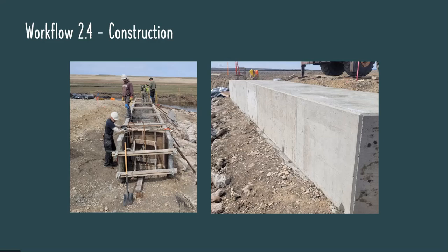You can imagine checking the elevations on this formwork with that construction model, I guess I'll call it, from Trimble Business Center. But also, as with any skewed bridge, there's some complexities that have to be accounted for somewhere for everything to fit together. And you'll notice, it might be hard to tell in this picture, but on the far end, that's a head-on line. And then this near side would be back online. And so the distance to the top of these caps is actually smaller here because the grade's coming down and taller in the back.